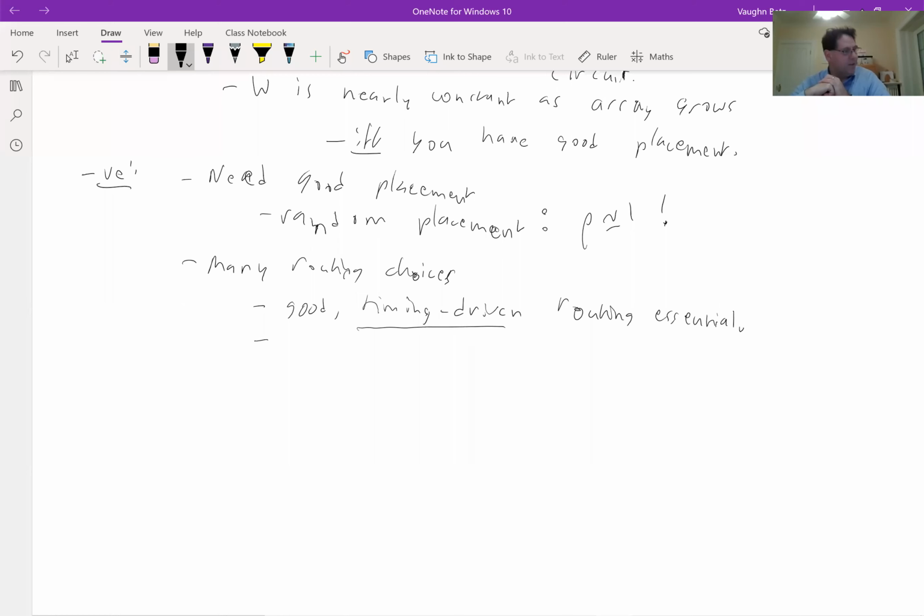So placement is optimized for best timing. Yeah, it means literally optimized for timing. It can be applied to any phase of the CAD tool. So a timing driven router means that the routing algorithm is timing driven. Generally, make sure the critical path is routed with priority, prioritize performance over area. So yeah, these are all correct.